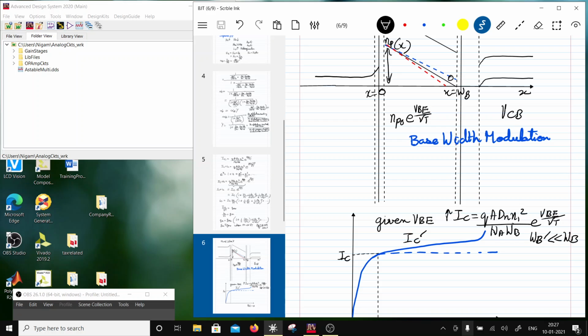This results in the delay of the signal, which is known as diffusion capacitance. Depletion capacitance is because of the space charge, while the diffusion capacitance is because of the delay in vacating the minority carriers from the junction, right?